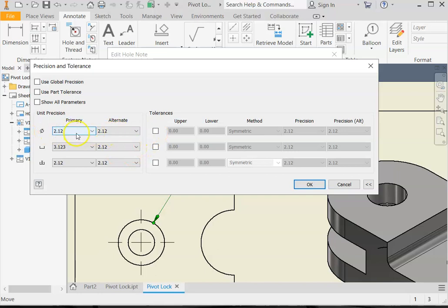And now we're going to check this box here for tolerancing for hole, not counterbore, for hole. See, this is the hole, the first one. We're selecting that. And then also we're going to use this method. Remember, there are different methods of tolerancing, which we will discuss in chapter 9. And then here we have limits stacked. This is more common because it already has done the math. We don't have to do plus or minus, then add ourselves.